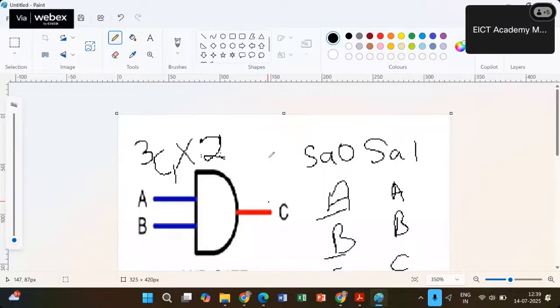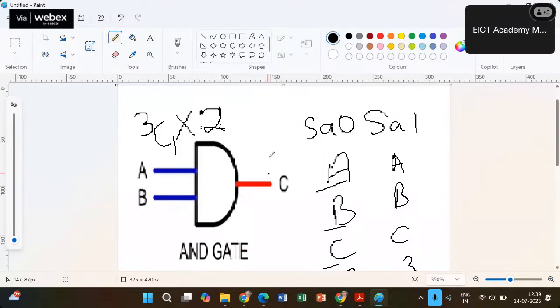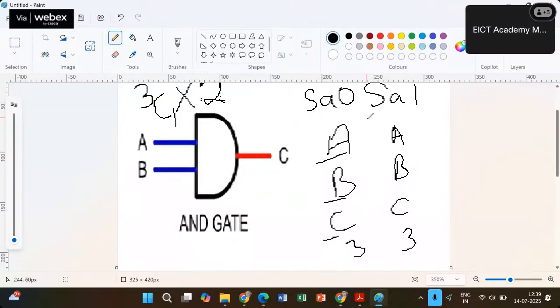Likewise, if I want to figure out how many double stuck-at faults I can have, I can have a combination out of these. I can choose one, and out of these I can choose one. But at the same time, I cannot have a stuck-at 0 and 1 altogether at one branch. So a single branch is mutually exclusive. So what I have to take? I have to take 2 combinations out of the 3. So the combinations will be 3C2 into. There are total 2 faults.